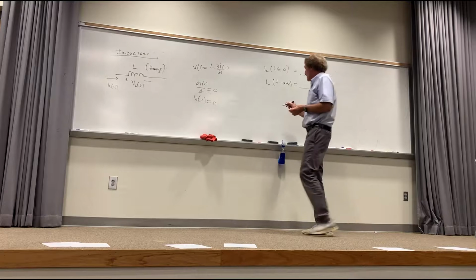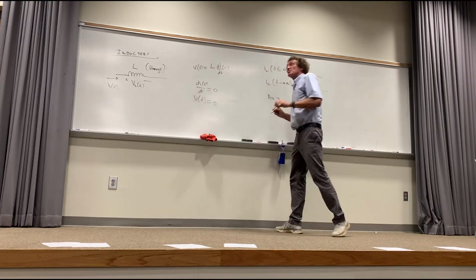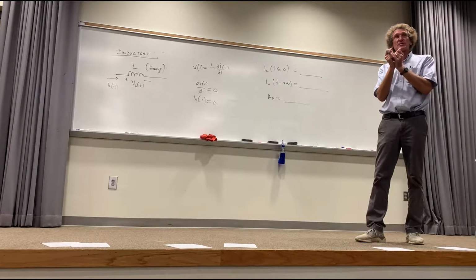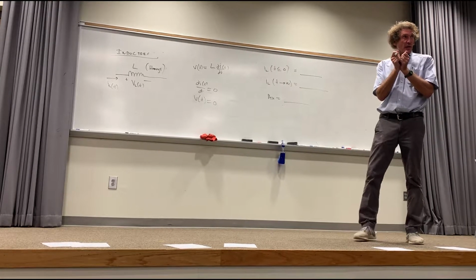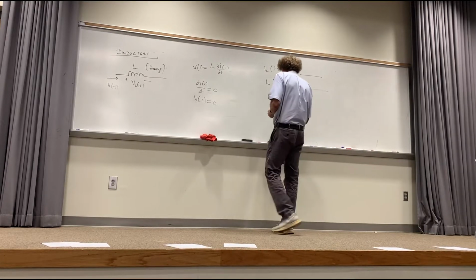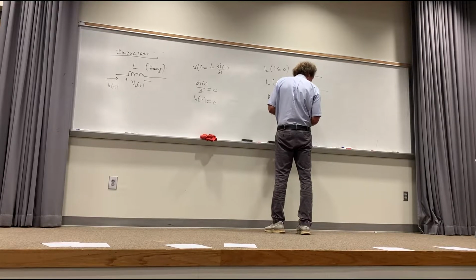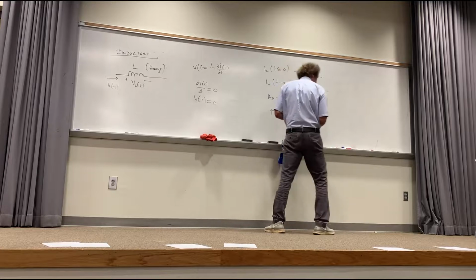And then we find our Thevenin resistance by turning off the switches and seeing what actual value of resistance is between the terminals when the inductor is removed. You follow me? Just like we remove the capacitor, here we remove the inductor. I'll be doing several problems to make sure you get this. With me? Then we find something called a time constant, tau. But now tau is equal to L divided by R.